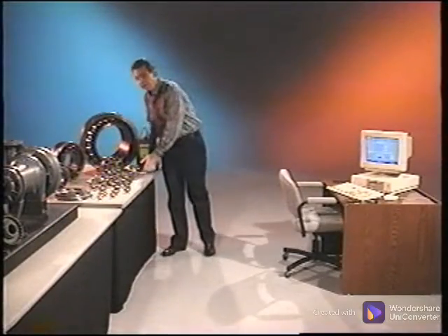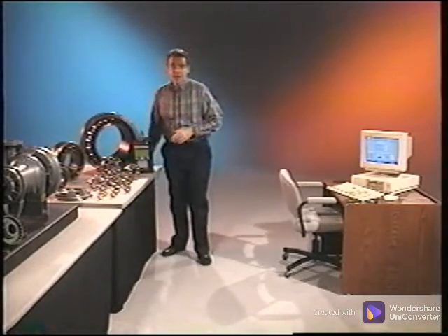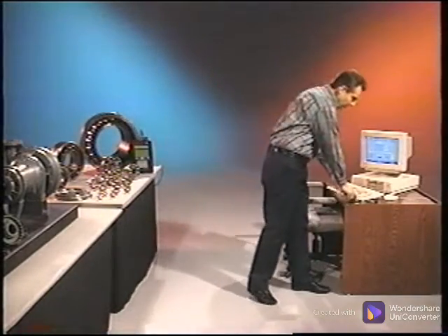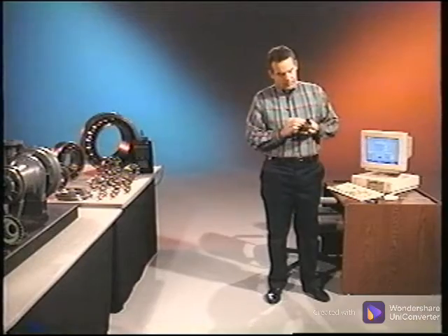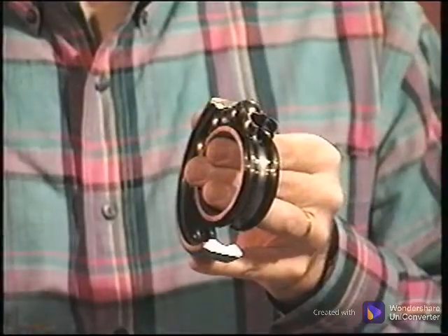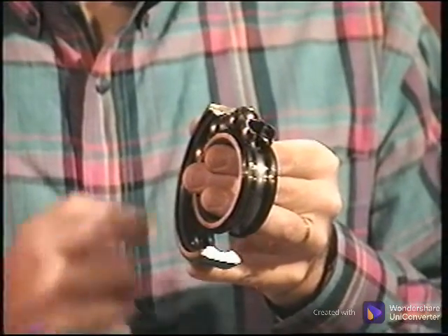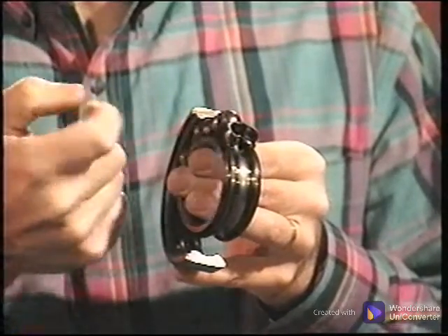Now let's consider bearing faults that can be detected using vibration analysis. Faults can be detected when there are defects on the inner or outer race, the rolling elements, or the cage. Other faults detectable by vibration analysis include looseness in the housing, excessive internal clearances, the bearing turning on the shaft, lack of lubrication, and a misaligned or cocked bearing.